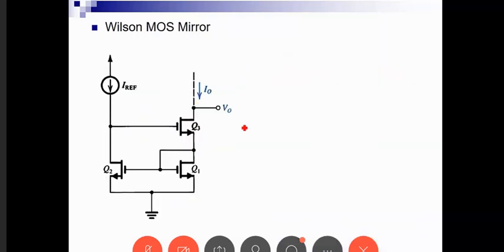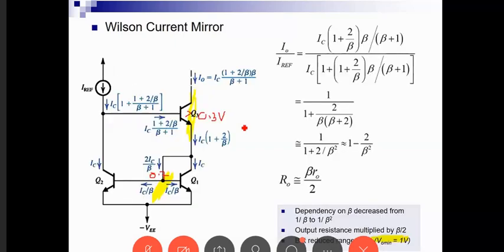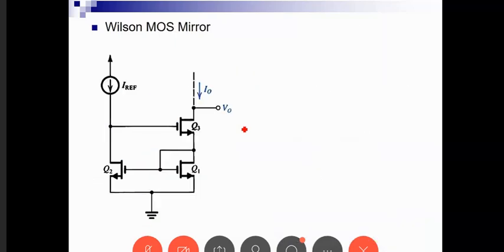Okay. So an equivalent circuit, like what we have for the BJT, Wilson designed an equivalent circuit for the MOSFET. He designed it in order to have a minimum number of transistors, satisfying mainly the condition for a large output resistance, because in the MOSFET he wanted to satisfy the large RO, which is achieved by stacking the two transistors on top of each other.